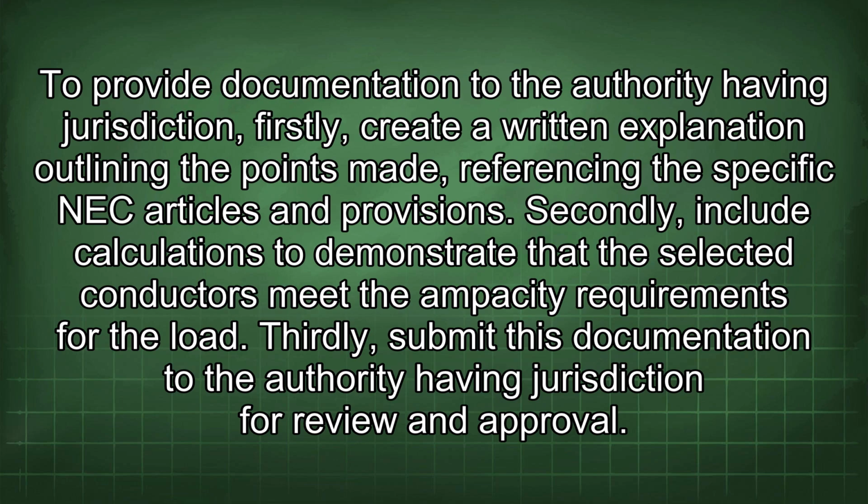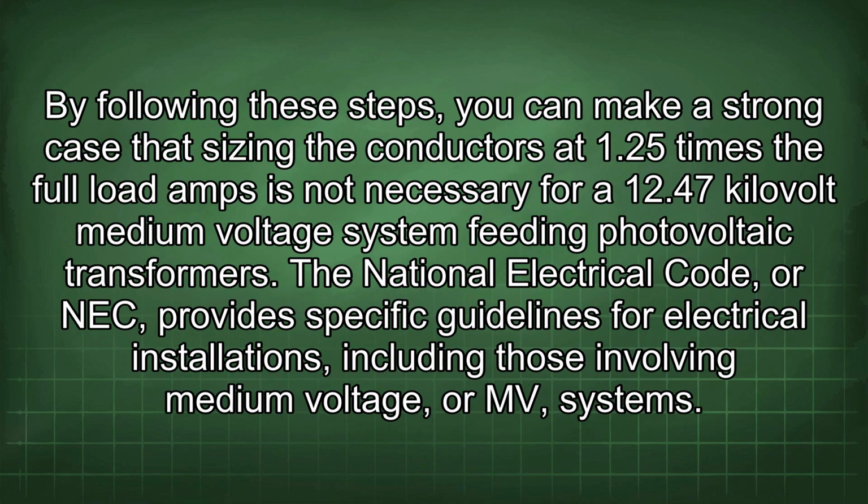Secondly, include calculations to demonstrate that the selected conductors meet the ampacity requirements for the load. Thirdly, submit this documentation to the authority having jurisdiction for review and approval. By following these steps, you can make a strong case that sizing the conductors at 1.25 times the full load amps is not necessary for a 12.47 kV medium voltage system feeding photovoltaic transformers.